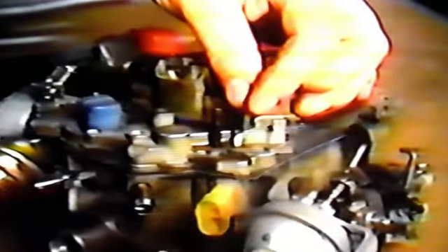The next step involves reconnecting the accelerator pump linkage. But first, you need to replace the little green plunger that was set aside earlier. Without it, no change will show up in the throttle position, and the TPS will not be able to function, especially in the power enrichment mode. After all the hardware is reconnected, go on and make the rich stop adjustment.